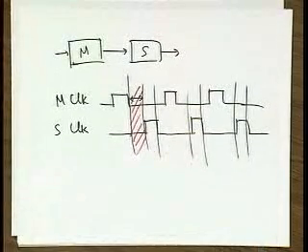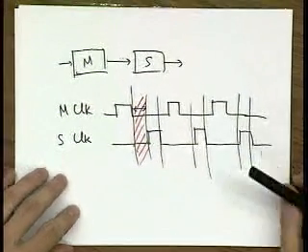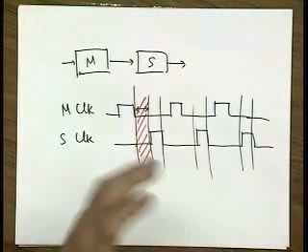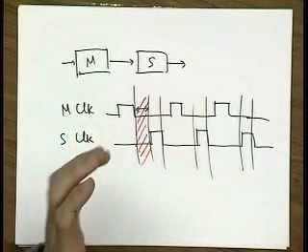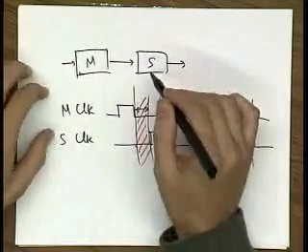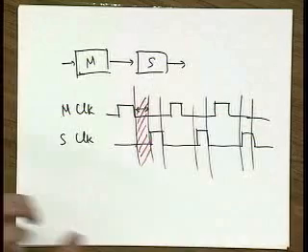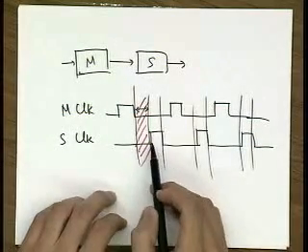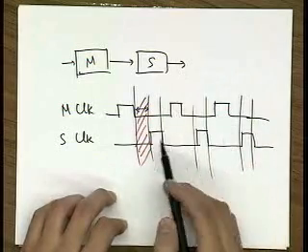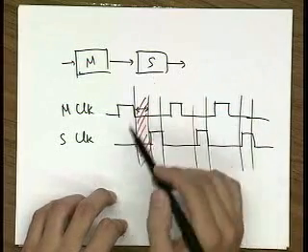The clock is showing you don't have the same timing for low and high. So right, this is just the concept. If you have the two-edge clocking approach, you have master and slave, and they both have a certain clock, maybe positive, maybe negative. But the idea here is that you want to eliminate this overlap period. This can also be negative, but for the purpose of illustration, I think it's easier to understand this problem this way.